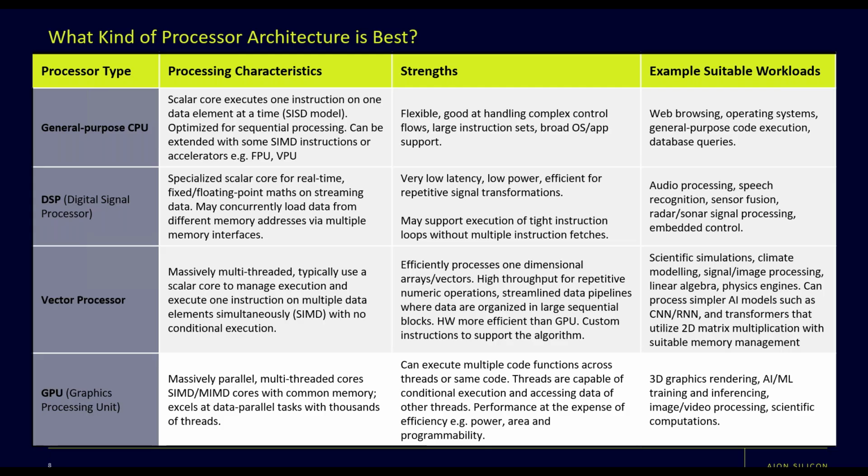And generally we can do very wide data. So it's very efficient for processing through large blocks of data, performing simple operations, numerical operations on that data set very quickly. To do that, it generally has a local vector memory to store that data so that it can efficiently access the data in the right format. However, it's not very good at actually navigating its way around that memory. It doesn't have any ability for conditional execution unless you actually augment it with some additional memory management technology.